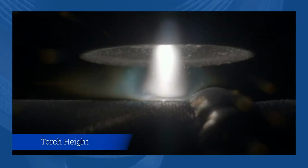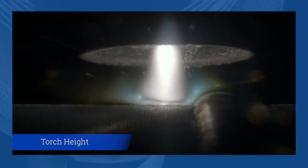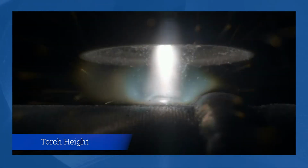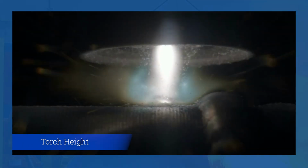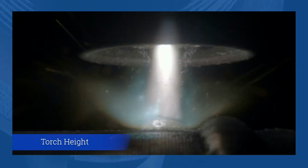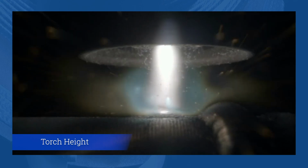So we're looking at the front of the weld because we want to discuss torch height. That's controlled by arc voltage, but what we're really trying to do is get those 2 powder columns you see entering from the top left and right to intersect immediately at the surface of the weld, right where the plasma column hits it. So everything's set properly in this video. Now let's go up. Now you see the 2 powder columns are intersecting above the workpiece. We're losing a lot of powder. We're making a bad weld.